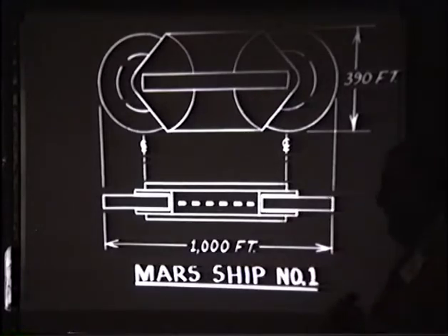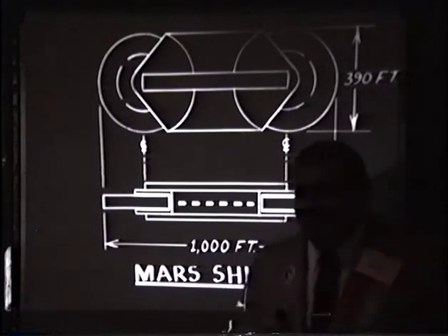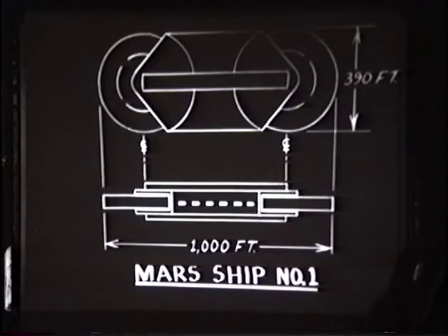Throttle control philosophy. There are people who have suggested, in the last couple of days of discussing this, that one could use the fuel flow rate for throttle. I don't advise it because of the radical change in thrust you get with just plus or minus a couple of milligrams at most any K factor, even 1%. The K factor, however, can be controlled very, very closely.